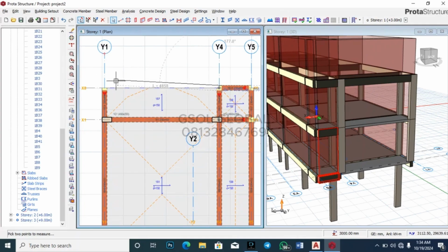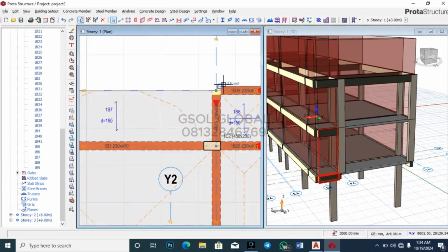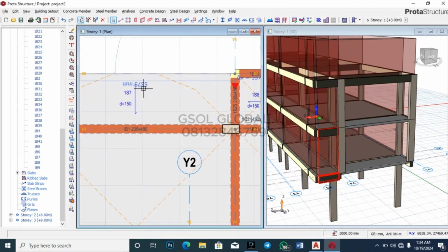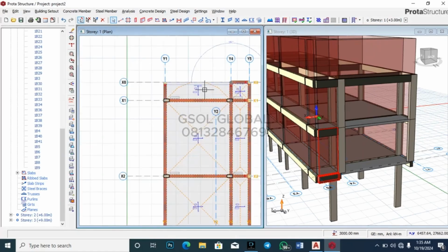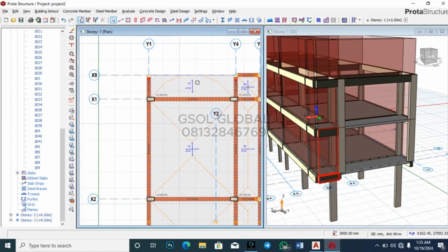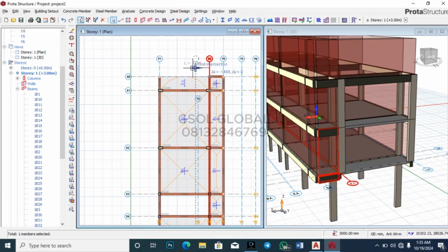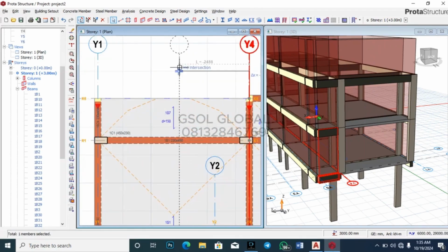With your shift key, then what are we going to be having? Let me measure from the middle to something. Okay, so what are you having there? 5375. Okay. So I'm going to offset 2.6 meters away. I'll click this, then offset axis, and drag to a point 2.6 meters.